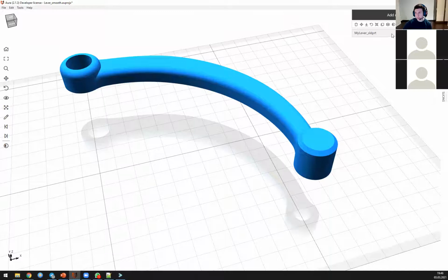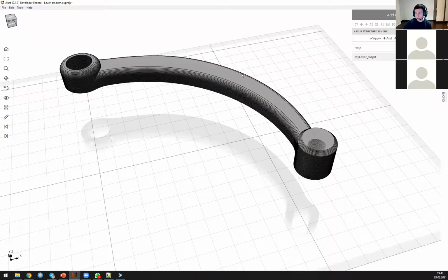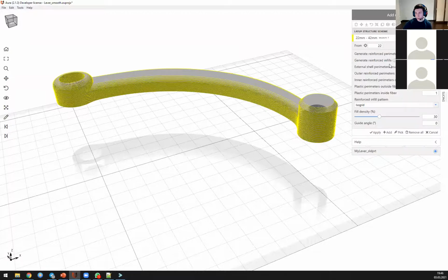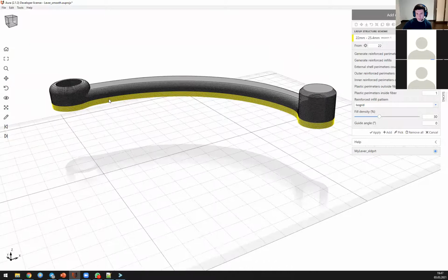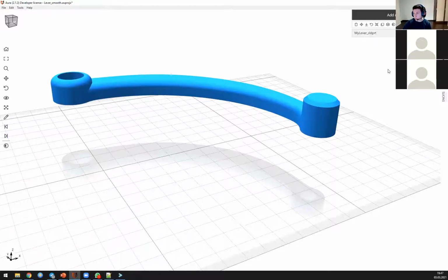And previously, we had another feature that allowed you to set a different internal structure of the part for different layers inside the part. So you were able to select different layers and set up a reinforcement scheme for these layers. And basically, masks are like a superset for this feature. So masks allow you to specify different settings, not only for different layers, but for different zones in the plane as well.